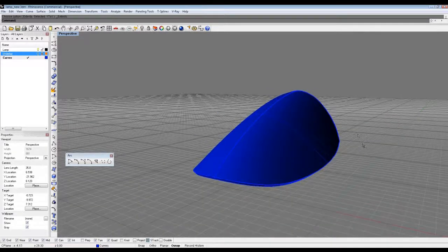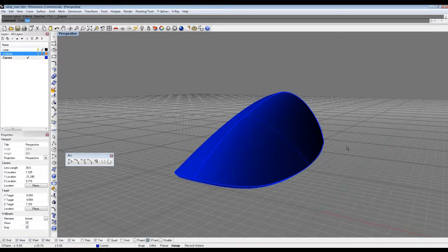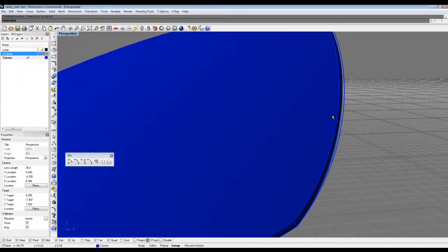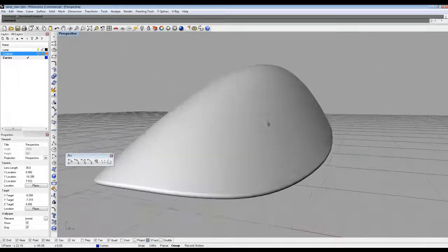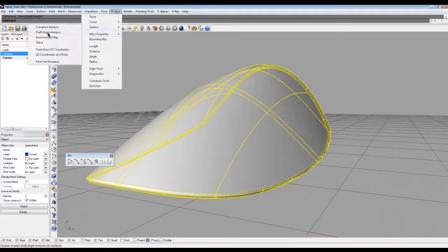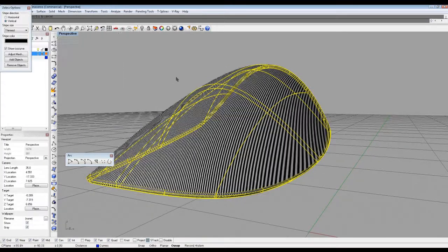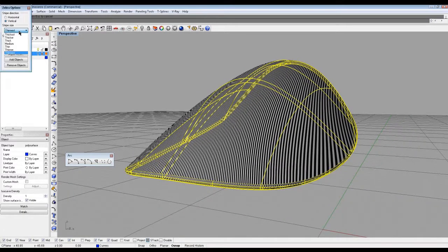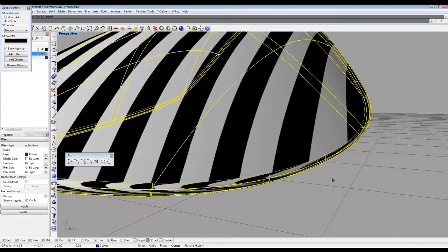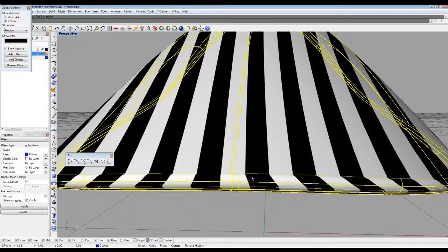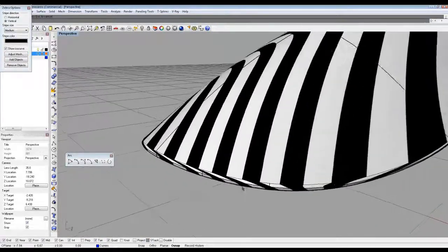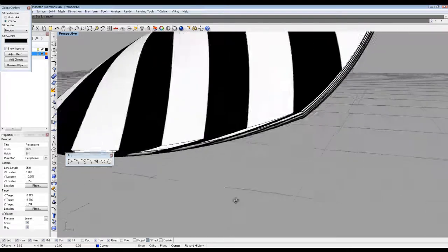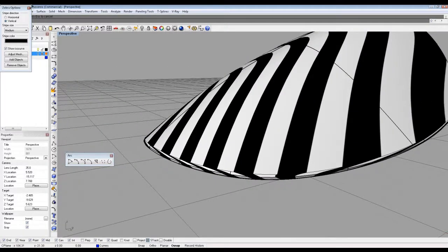And I'm also going to fillet the edges, because who doesn't like fillets? We'll make that 0.060, and yeah, check that out. It's pretty good. Now I could come back in here and analyze the surface just to make sure it's nice and pretty. I'm using the zebra tool to do that. And you're going to see there's a little bit of a break in continuity as far as how everything flows. But if you really want to get into that, there's plenty of videos on surface continuity that you can learn about that sort of thing. But for us, this will do perfect.